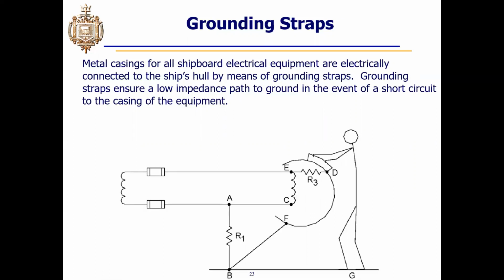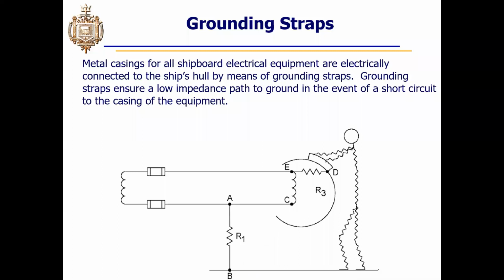So the whole idea is that it provides a positive electrical path from the metal cases of ship's components to the ship's hull, so that even if they are shorted, there's no way they could become a shock hazard to people.